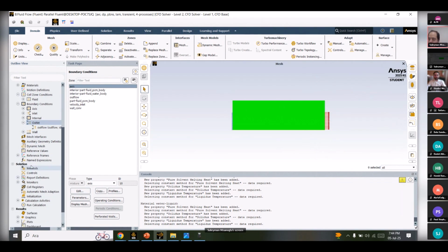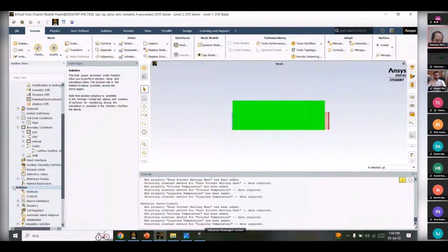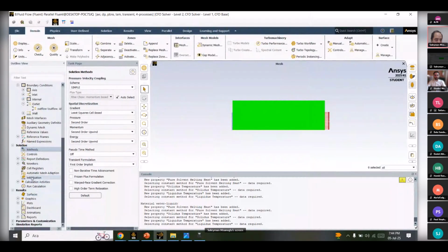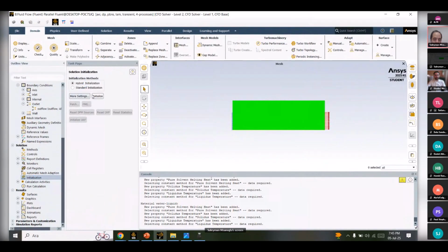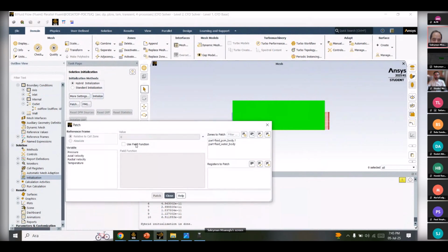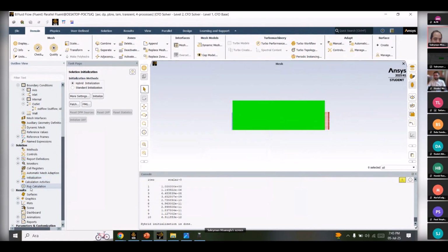Finally, let's set the solution algorithm to SIMPLE, meaning semi-implicit method. Here, solution method, SIMPLE, okay. And normally I use PRESTO for convergence, but this time we use second order. Now this is demo. Okay, and we click patch for initial condition, initial temperature, 300 Kelvin. Everything is 300 Kelvin. Everybody is 300 Kelvin.